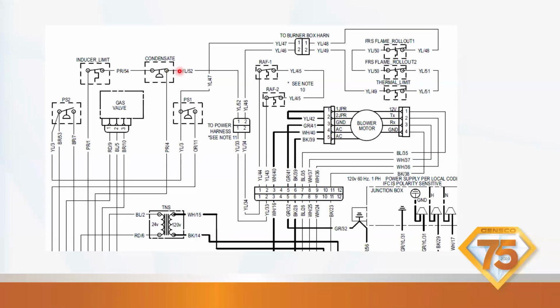So as we leave that condensate switch, you'll see it goes over here to a plug, right? A harness, a wire connector, right? And it goes out of that one to another plug, a big old 12-pin plug here. And then this one goes up to our, this is actually this plug, if you pay attention to where this is, where it goes into the blower compartment. Because you can see the blower motors right here. Here's these switches, right? They all go through that plug.